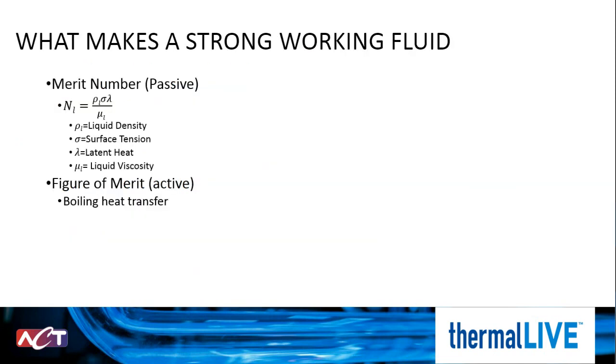Typically, in pumped two-phase designs, we will use refrigerants as the working fluid, as opposed to water in some of our passive solution examples. Now, we talked a lot about the latent heat of vaporization of water being a factor in the effectiveness of heat transfer. But it's important to understand what makes a strong working fluid in a pumped two-phase design.